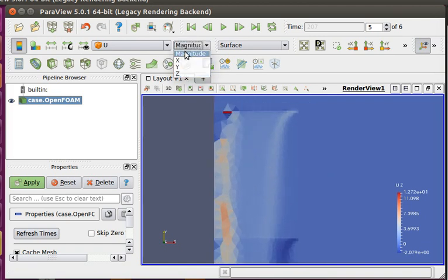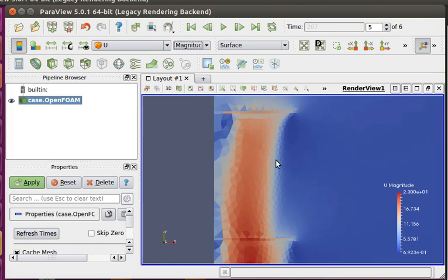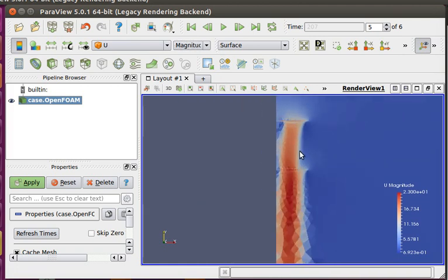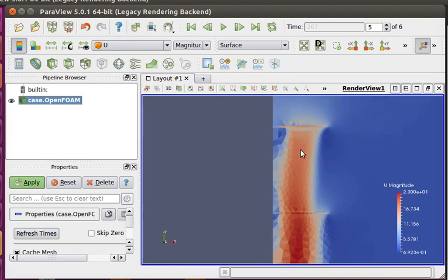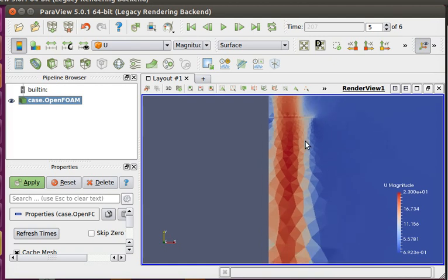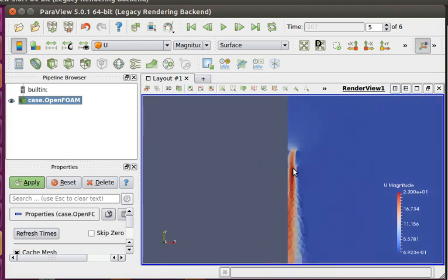But anyways, the flow field on the whole looks very reasonable. You have the stream tube contraction and an increased velocity after hitting the second propeller. It's a very coarse mesh, but you can easily get better results by refining this.